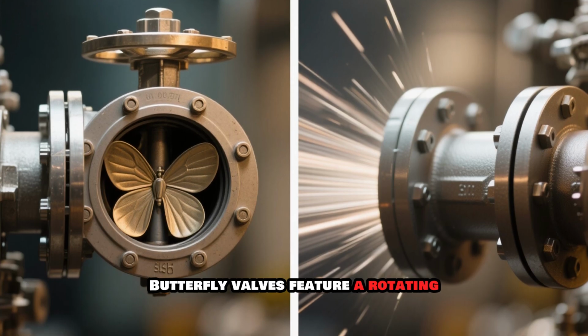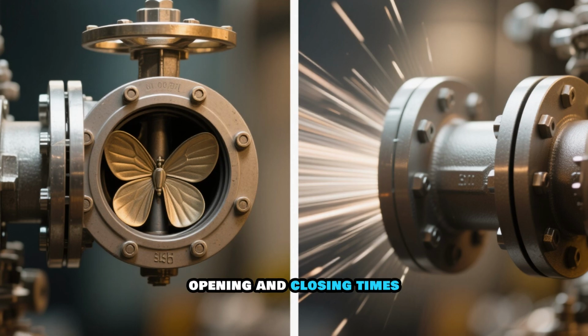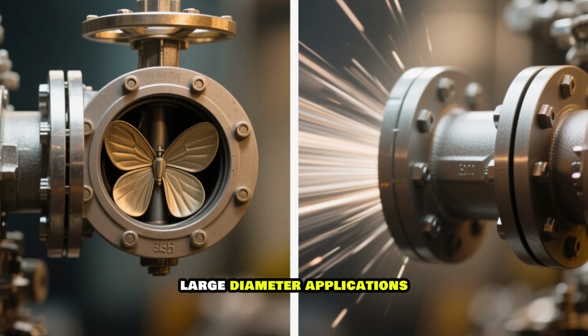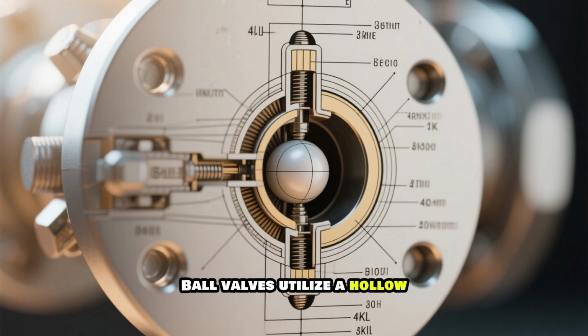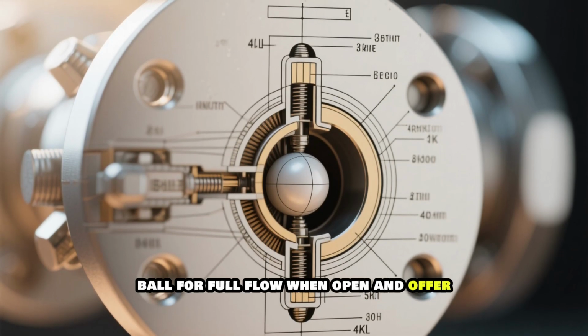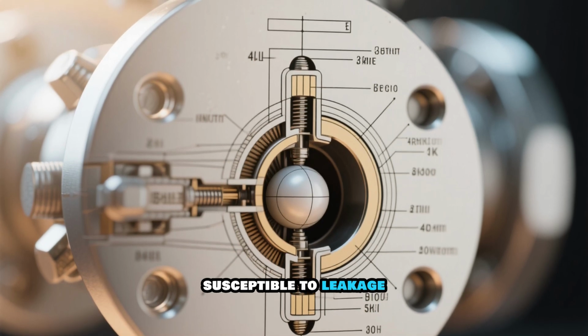Butterfly valves feature a rotating disc for flow regulation, providing quick opening and closing times, and are often used in large diameter applications. Ball valves utilize a hollow ball for full flow when open and offer good shut-off capabilities, but may be more susceptible to leakage.